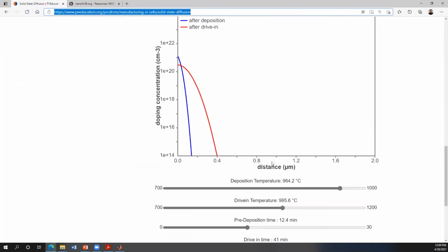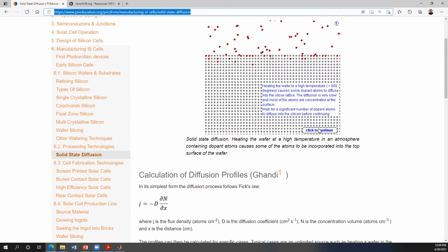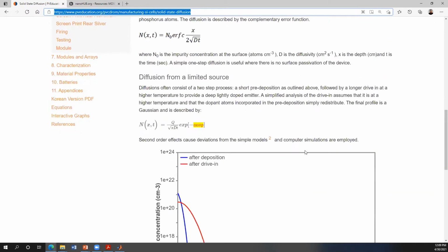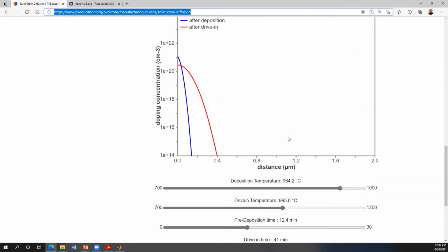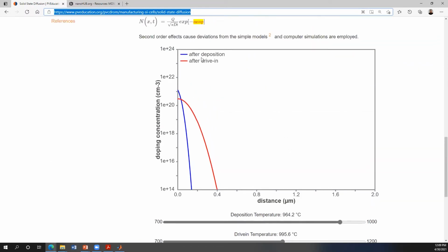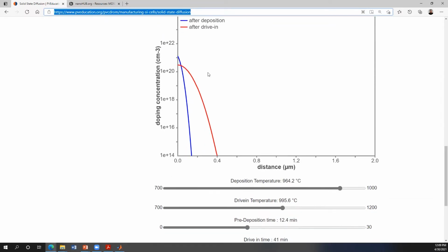So let's say we have a chance to get a concentration distribution analysis by taking a cross section into the depth. From here, I'm just taking a cross section. Okay, so there are two phases of this. First, I do the deposition of the dopant, the material. Then I will do the drive-in by employing the temperature, and then we will be able to diffuse the dopant more into the depths.